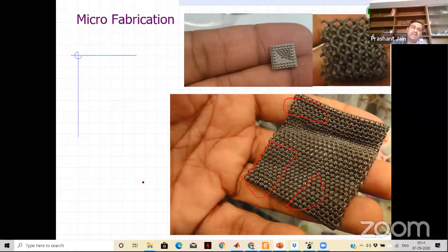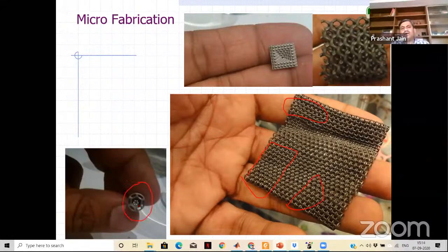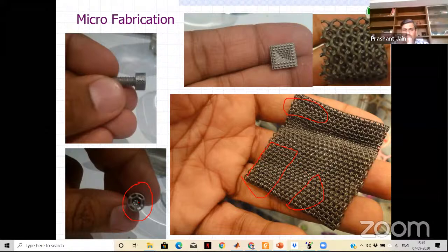Look at this here, a small screw of titanium. This is used to implant in a human body. But the requirement is for tissue to grow and pass through these screws. Look at this here, the through holes are required. Even for the cross section, you look at, right? These are the through holes. These small size holes cannot even be built by the wire EDM. Right, so these are the typical applications of additive manufacturing in a metal additive environment.